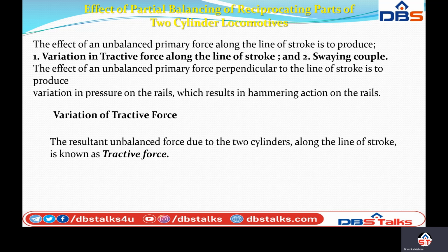Due to this partial balancing of reciprocating parts, there is an unbalanced primary force along the line of stroke and also an unbalanced primary force perpendicular to the line of stroke. We need to remember both.